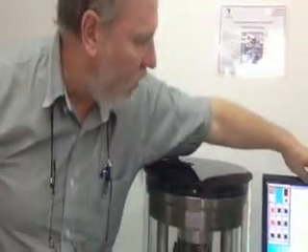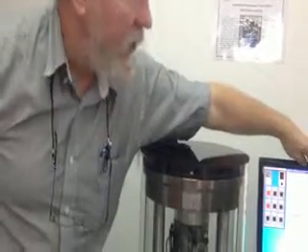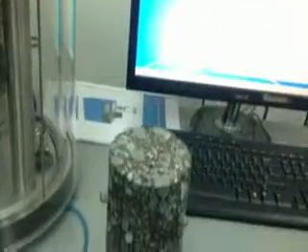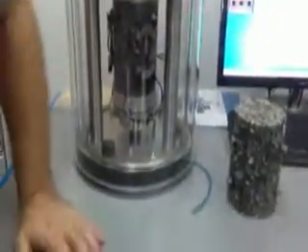so if we now go, when you're ready to start your test, you check your levels to make sure your transducers are in the range. You can check your temperature to confirm that your temperature is in your range. This says this level is suitable. So we have 32 degrees on here, it's okay, it's inside the range.